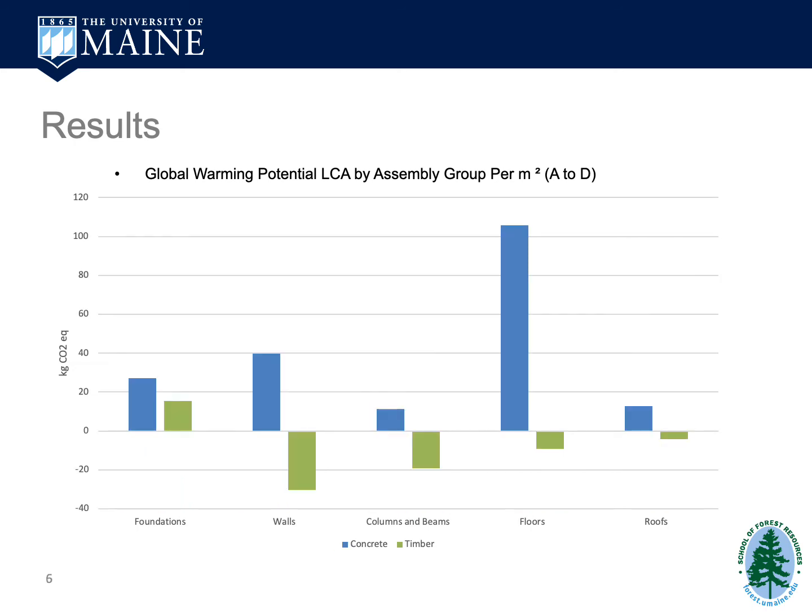The total global warming potential of the mass timber building is 5 times smaller than the concrete building when considering the benefits beyond the system boundary because of the carbon sequestration benefits of the material, here represented as negative values. The carbon sequestration benefits, or biogenic carbon, accounts for the carbon dioxide removed from the atmosphere and converted into wood.